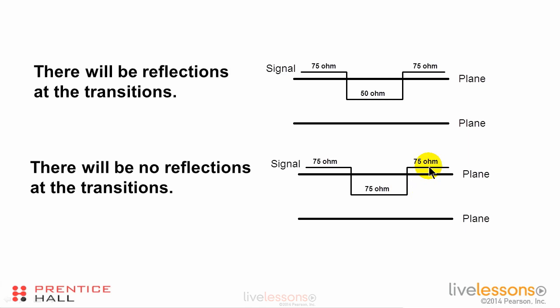that layer. Now remember, the way we got a controlled impedance trace is by controlling the relationship of the trace width, the trace height above the plane, and the relative dielectric coefficient of the material, and to a lesser extent, the thickness of the trace. Well, if we go from one layer to another, we are probably changing at least one of those parameters.